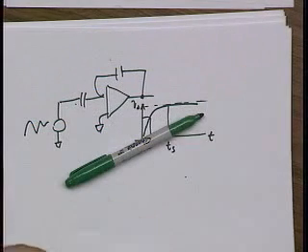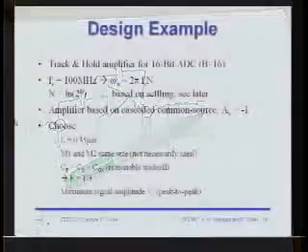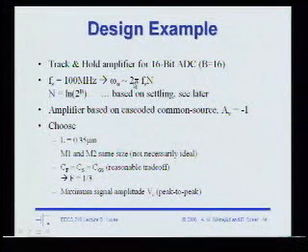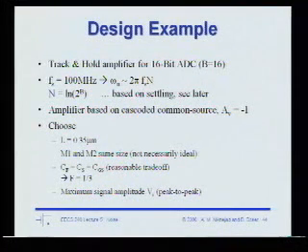Okay? And we're going to do this more careful calculation later, but for the purpose of this example, you can see very simply that the number of time constants that you should wait is related to the number of bits of accuracy you want. Because the settling time is an exponential process, it's the inverse of that, so you get a log relationship.